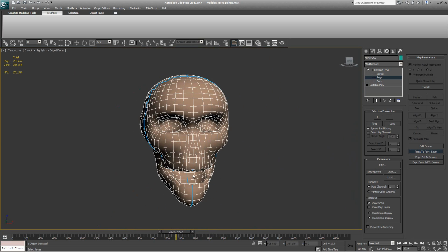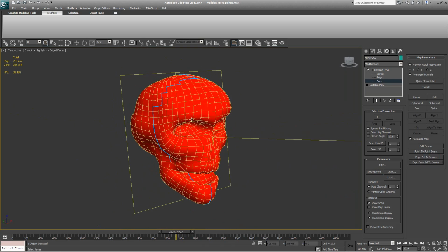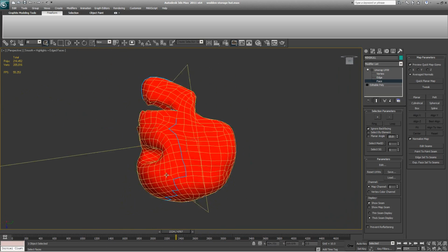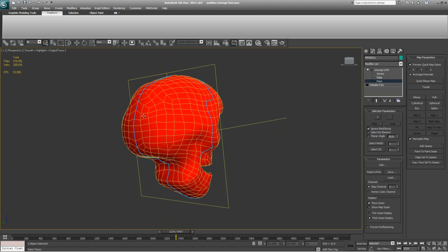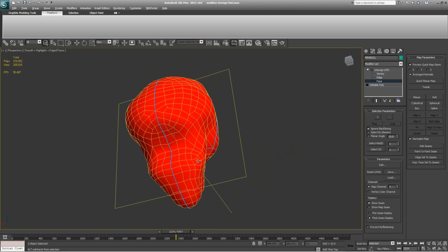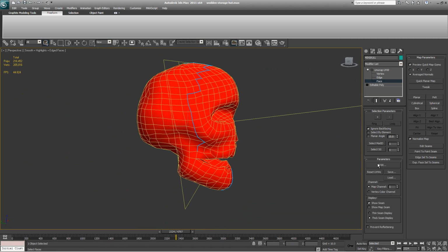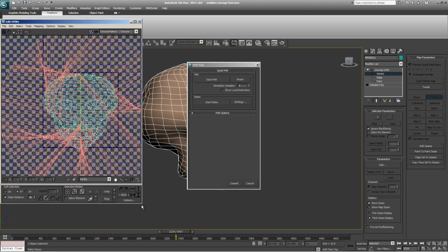We can go and press 3, go into the face mode, click on one of the faces and click this button here. So this expanded this polygon towards all of the seams, and because all of our model got red, it means that our seams do not cut out solid parts. So they all form somewhere nicely, and when we unfold this model, it will be one solid piece. And we can go into edit and we can go into pelt. This is probably something new to you.